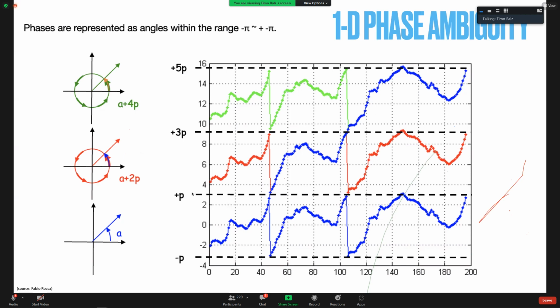Again, what we see in the data would be that part below. That's what we actually see. And in phase unwrapping, we try to combine them so that we go beyond just minus pi to pi, to 3 pi, 5 pi, 7 pi, and so on, to unwrap along and get some absolute phase value.